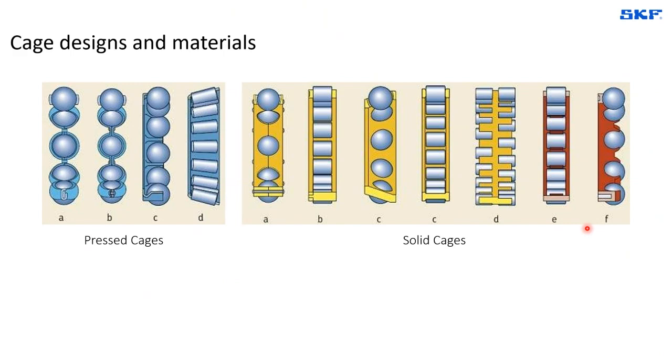There are different cages that, for example, interact with the rolling elements, the balls or the rollers, or with the rings in different ways, depending on their configuration within the bearing. This means that a cage will have some normal contact areas, while other surfaces are not supposed to be in contact. If we don't understand the design of a bearing, it will be difficult to judge if the evidence of some contact in a particular surface of the cage is supposed to be there or not.